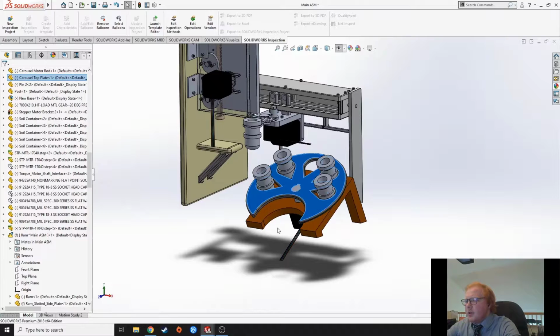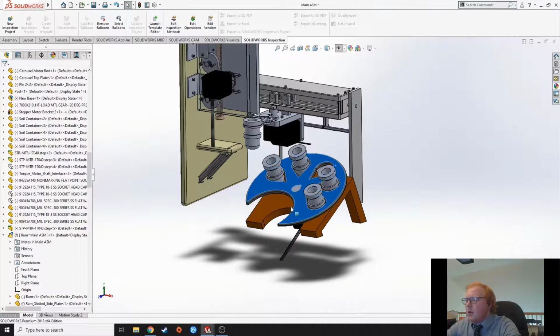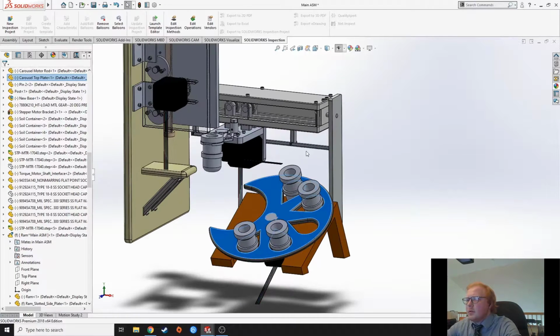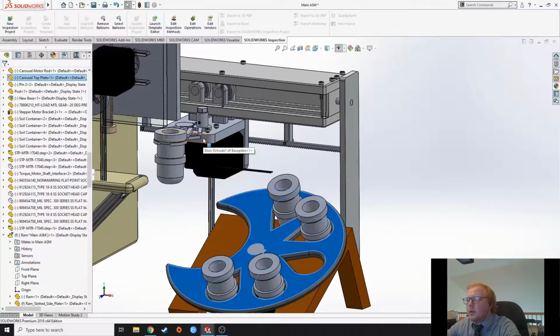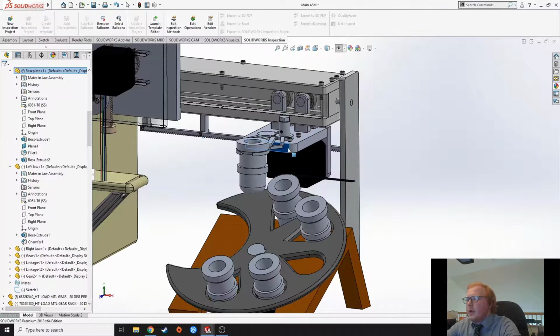The reason for this design was so that the drill could have clearance to drill into the regolith, and also allow for easy collection of the sample from the drill. So this allows the sample container to be rotated once the drill has picked up the sample, and then shake the sample into the sample container. From there, the plate will rotate the sample, whichever one is looking to be analyzed at the time, and this gripper jaw assembly can move down the rail to pick up whichever sample container.